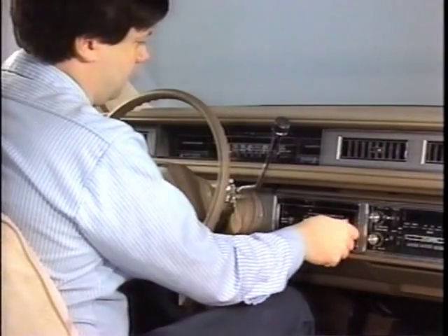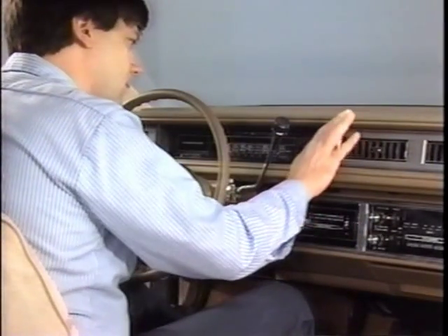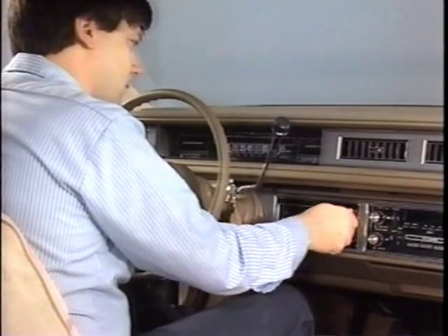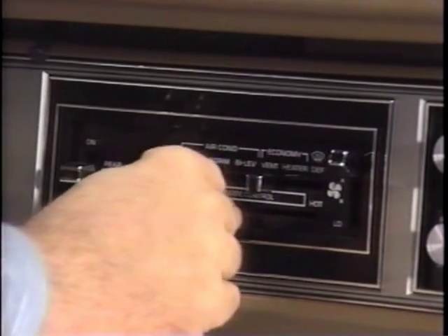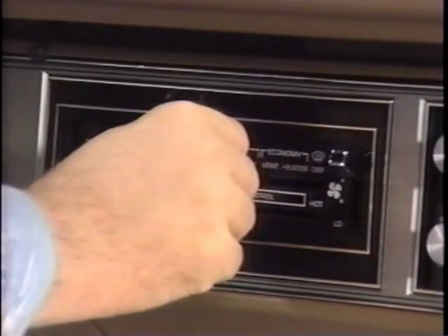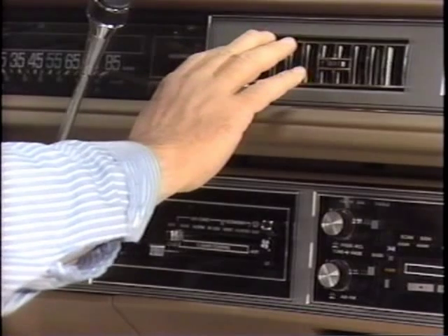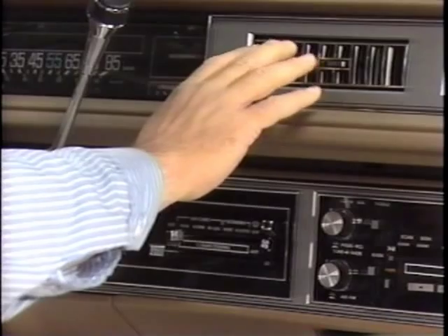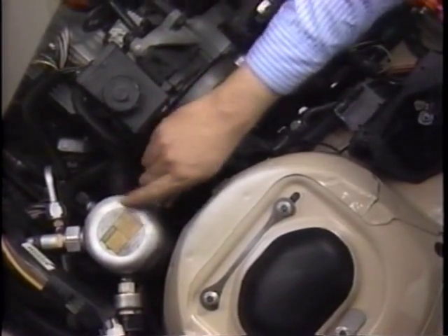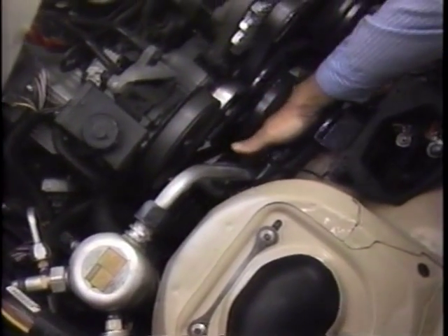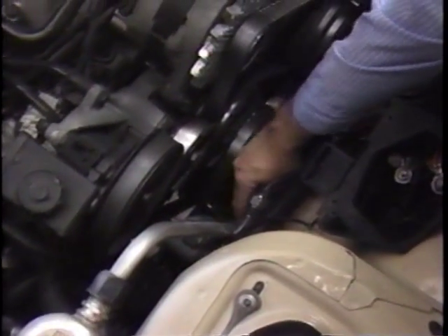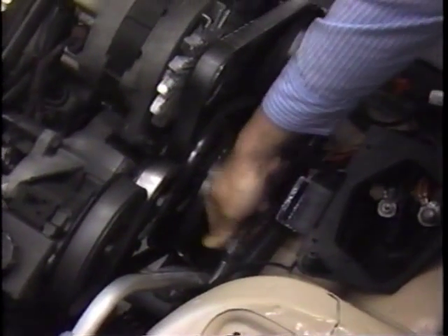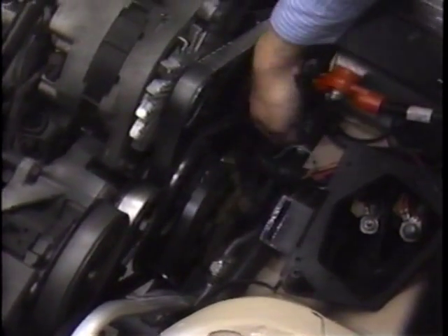Begin any diagnosis or checkup with functional checks. These will verify the customer complaint, if any, and reveal any additional problems. You may even find the cause of a problem in the course of performing these simple procedures. At this stage, you can also use the self-diagnostics available with the ETCC and graphic display systems. If the functional checks don't lead you to the cause of a symptom, a visual inspection might. Again, these are quick procedures that can often reveal the source of a problem without extensive testing.